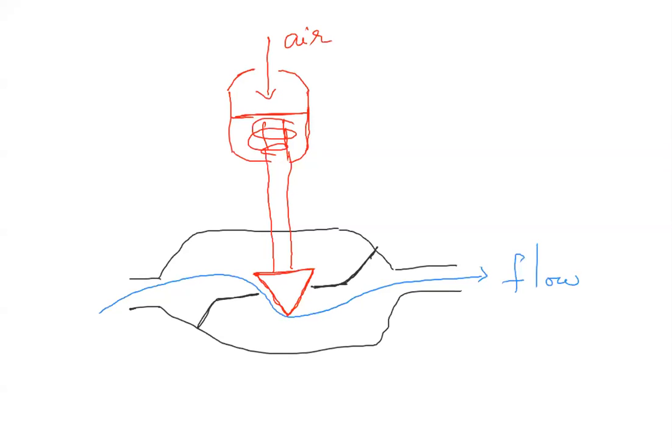Is this air to open or air to close? If you apply the air pressure, then the wall moves in the downward direction. Then the opening closes, no? Then the opening closes because this is the opening which is available. So if the stem comes in the downward direction, then the entire wall closes.